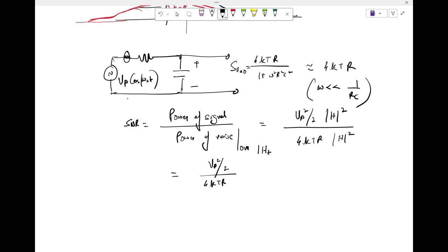But is there a trade-off? Is there something I am paying with? Because everybody can do this. So what's the problem? I take a circuit, I reduce R, increase the capacitor. Is there a penalty anywhere, or is it a free lunch? Power dissipation. Where is the power dissipation? Area is a problem, I agree, because if you keep on increasing the capacitor, on-chip area will also take a hit.